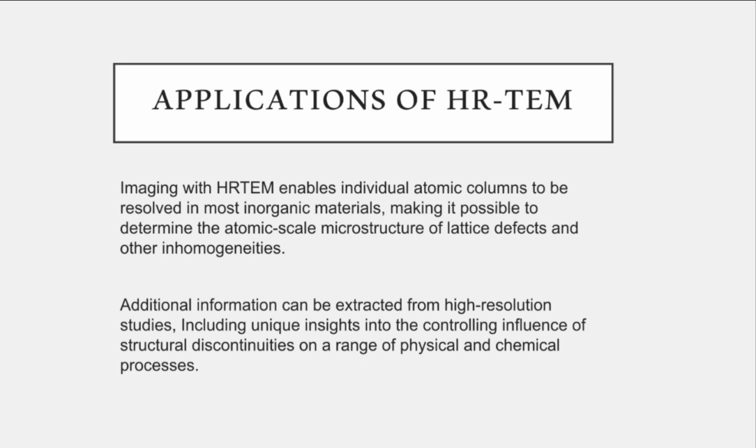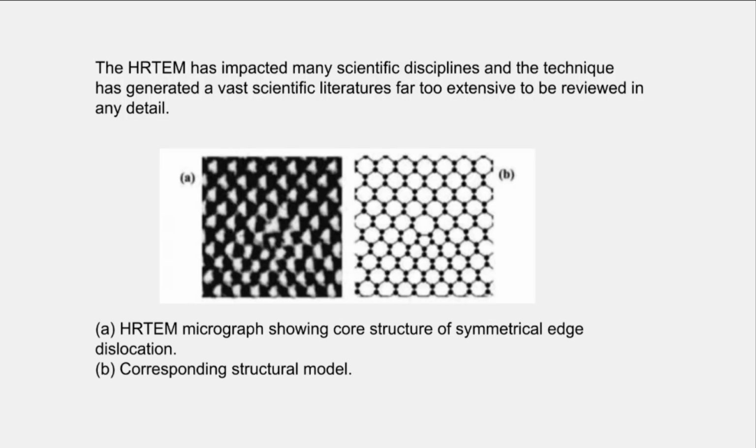Now on to the last topic, applications of HR-TEM. Imaging with HR-TEM enables individual atomic columns to be resolved in most inorganic materials, making it possible to determine the atomic scale microstructure of lattice defects and other inhomogeneities. Additional information can be extracted from high-resolution studies, including unique insights into the controlling influence of structural discontinuities on a range of physical and chemical processes.